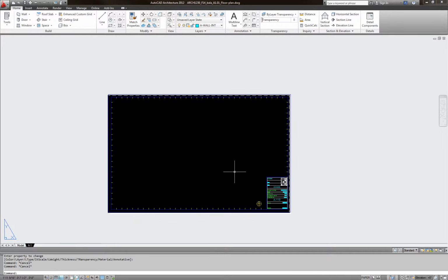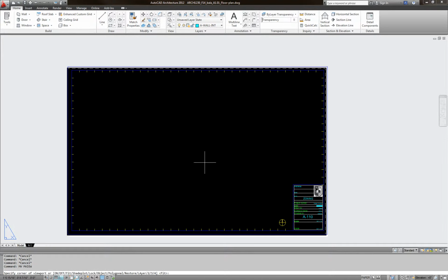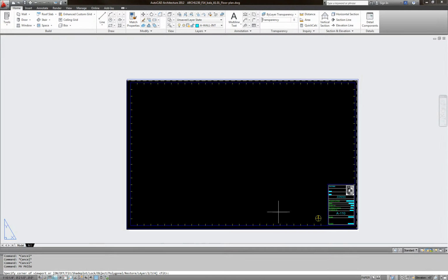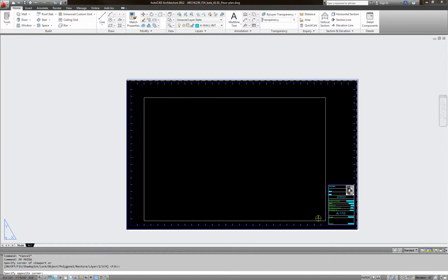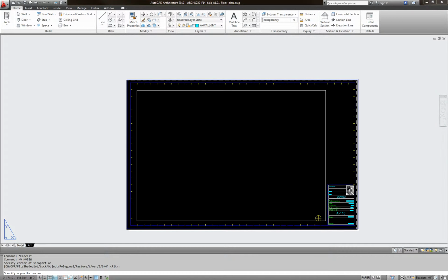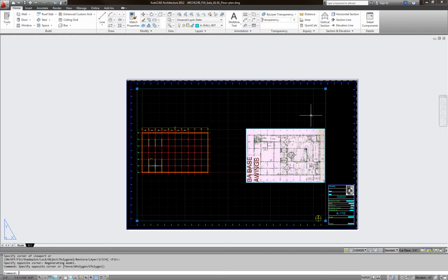But guys, I'll do another video tutorial with more depth on how to print an XREF. I'm just going a little fast because people have to do this assignment for tomorrow. So MV for viewport. Okay guys, MV. I can create MV, click the first point, and now click on the second point. See that it'll give me the viewport.